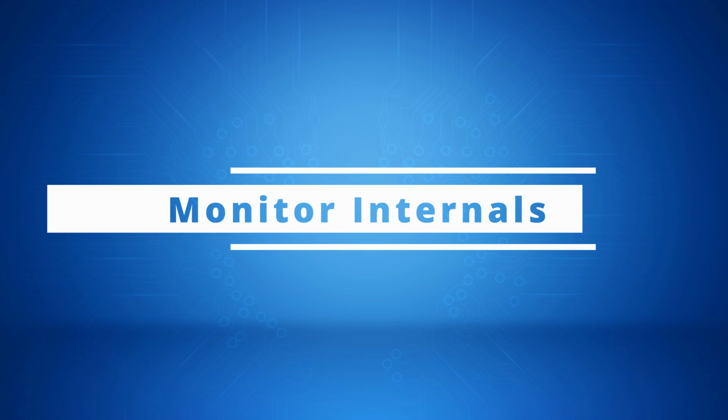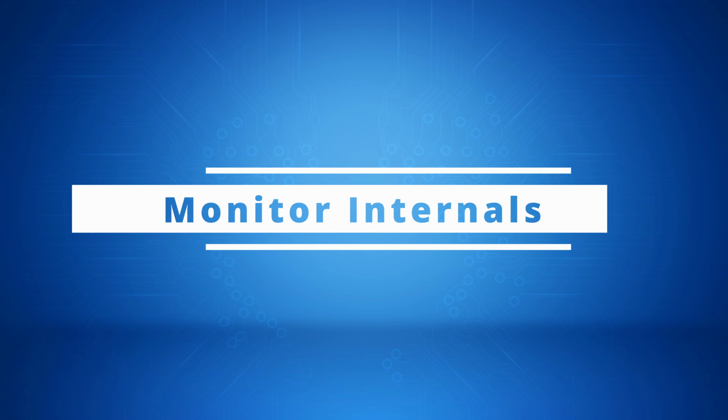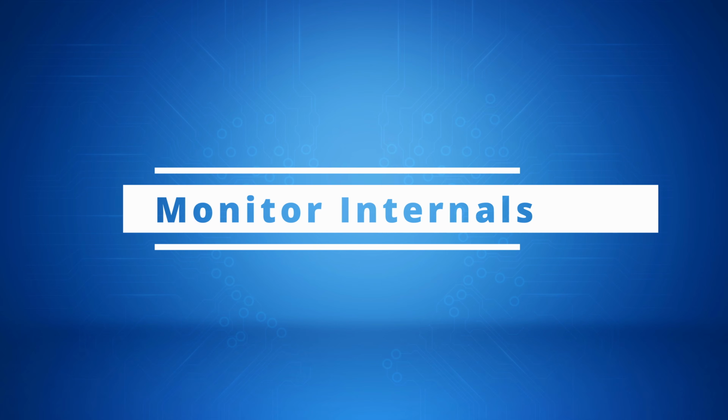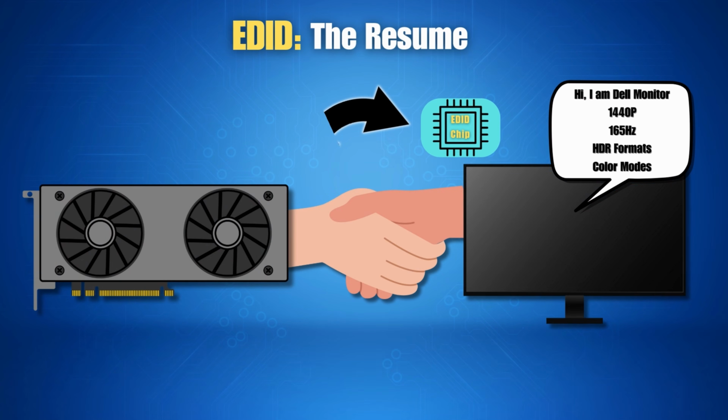And so now that we have our compressed, packetized, or TMDS-encoded data stream, we have finally arrived at the monitor. The journey is almost over, but the monitor itself has a few key players to finish the job. First, the EDID. The very first thing that happens, even before you see a picture, is a handshake. The moment you plug in the cable, the monitor sends a small chip's worth of data back to the GPU. Think of it as the monitor's resume. It says, "Hi, I'm a Dell monitor. I support 1440p at 165 Hz. And here are the color formats I understand." This is how your PC knows what resolutions to offer you in the settings.